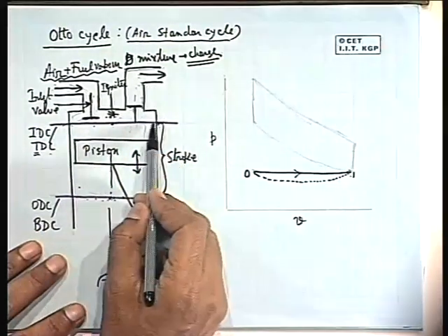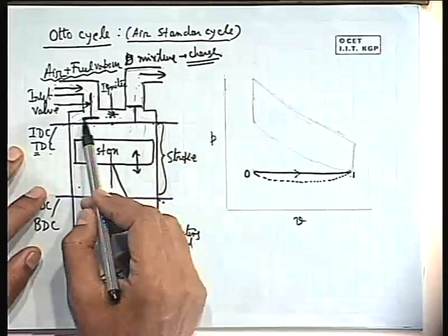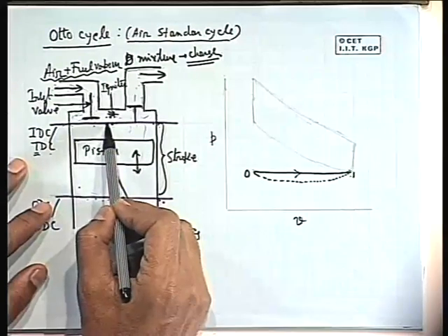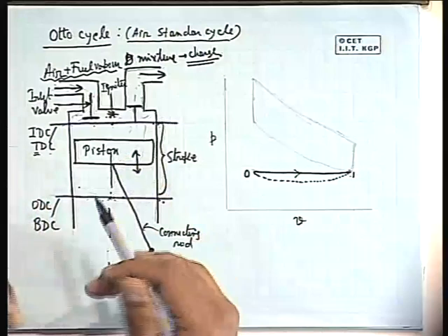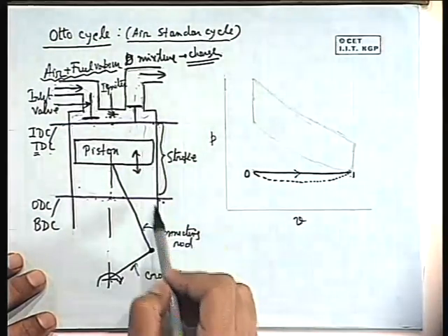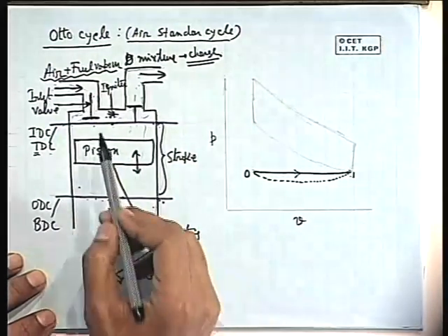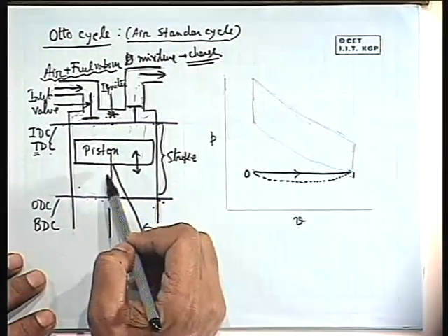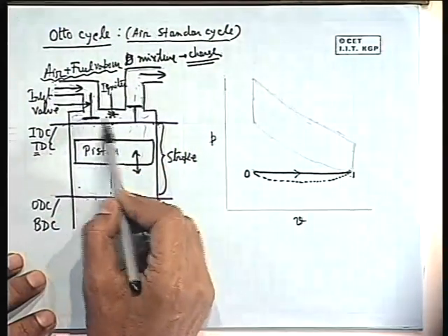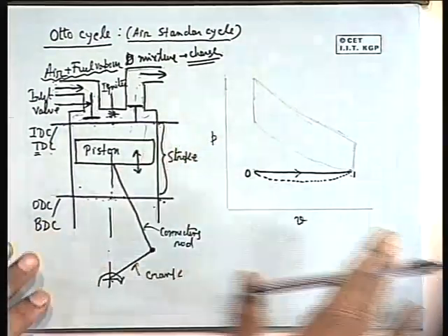So when the piston again comes to the inner dead center position, or top dead center position, it comes to its initial condition, that means this volume is full of charge, that is, burned products of combustion. Then again the piston moves downward to start another cycle. So this way the cycle of events repeats. One cycle is composed of 4 strokes, that means 4 movements of the reciprocating motion of the piston between IDC and ODC. Then when the piston starts descending again, it inducts the fresh charge, a mixture of air and fuel vapor. Along with that, the products of combustion are also there, which get expanded, and that causes some other problems which I will not describe here.